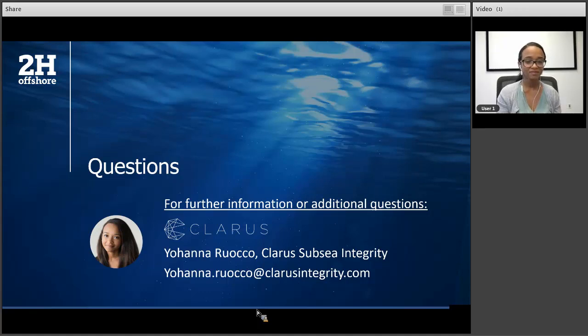Okay, let me see. First one, was ILI considered for the flowline case study? We did look at ILI. The field had not been operationally pigged, so there was no cleaning that was done of the pipeline. So the risk associated with conducting ILI was considered too high. In addition to that, we would have had to do a bidirectional pig at that time because the flow loop was not available, which also increased the risk and cost. So the goal of our assessment was to identify if ILI was really a requirement, and we identified risk areas to do NDE and to evaluate and screen for corrosion before even recommending ILI. But we did evaluate it.